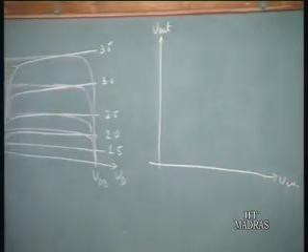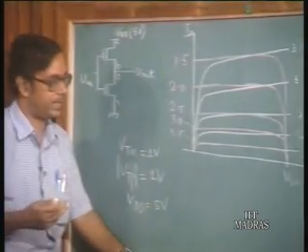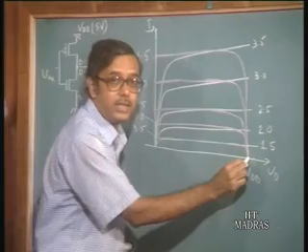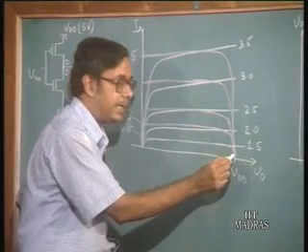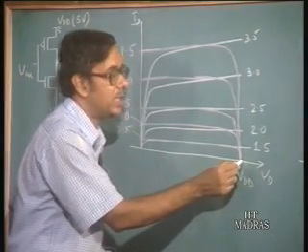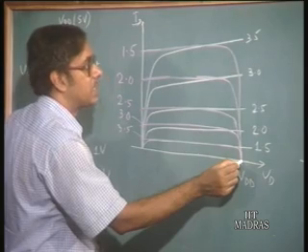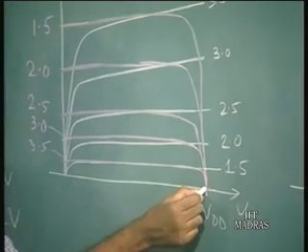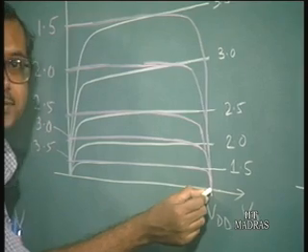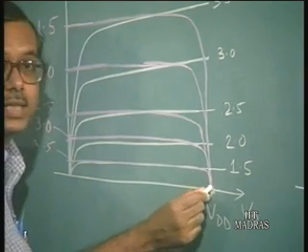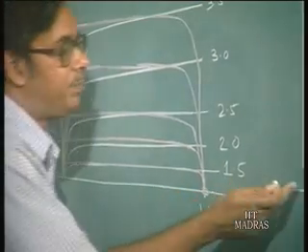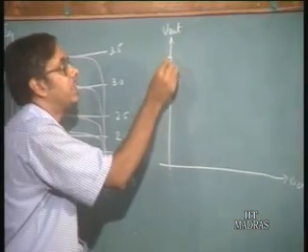Now, when the input voltage is 0 volts, say, the characteristic for the NMOS transistor is going to be along the x axis, because the gate voltage is less than the threshold voltage. And the gate to source voltage of the PMOS is minus 5 volts. So, the point of intersection is actually going to be right at VDD. So, when the input voltage is 0, output voltage is VDD.